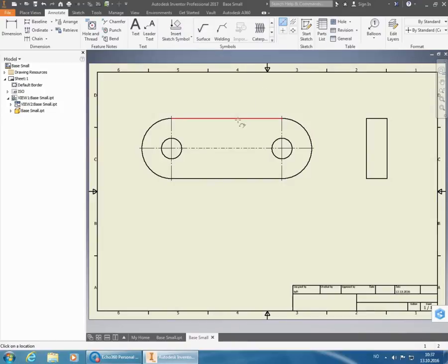We can also have a center line going from top to bottom along the middle here to show that it is also symmetrical across on these sides, so it's possible to mirror it that way. And since we have the symmetry line going across here, we should put it on the projected view also, just to show where all the symmetry is.